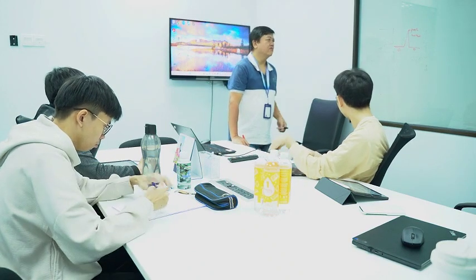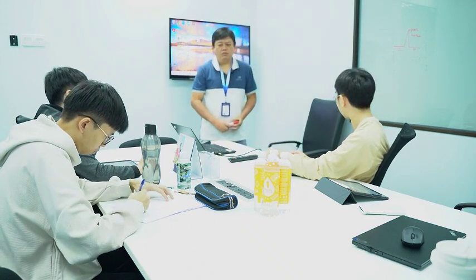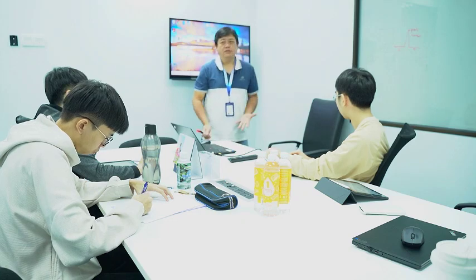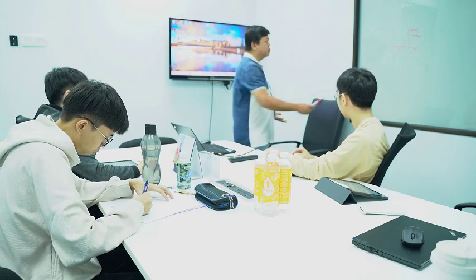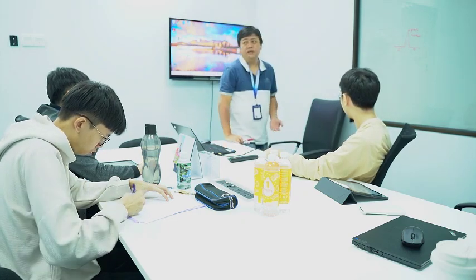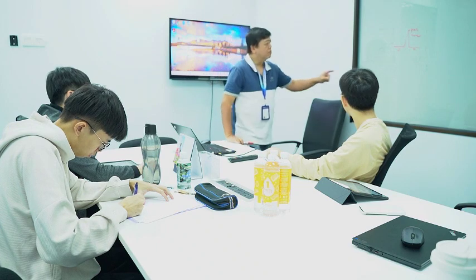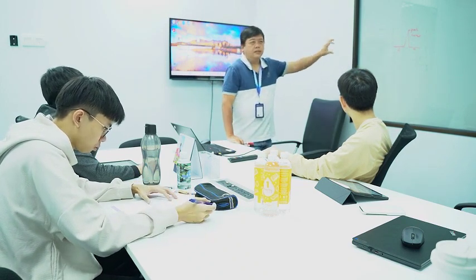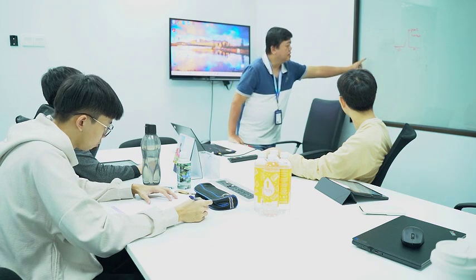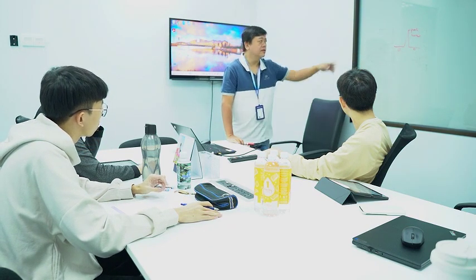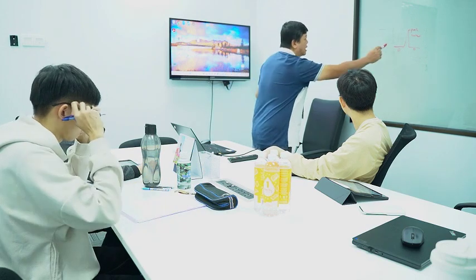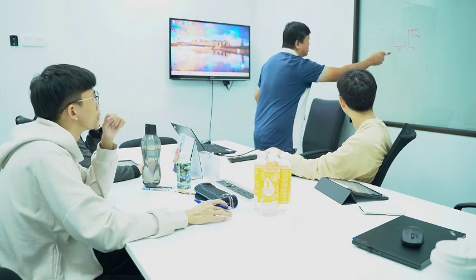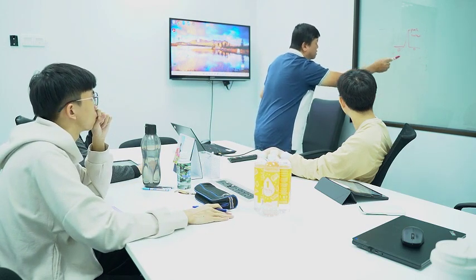So I try to give you an overview of how important the R-on is, okay? But in this part, it still depends on R-on also. So you have to get the right timing for that. But at a particular moment at the center here is saturation, right? But there's some time here in the linear region, it depends on the R-on of your circuit, like the inverter here. That's why I told you this is R-on, right? If we increase the size, we reduce R-on. So your RC constant reduces, so your charging will be faster, right?